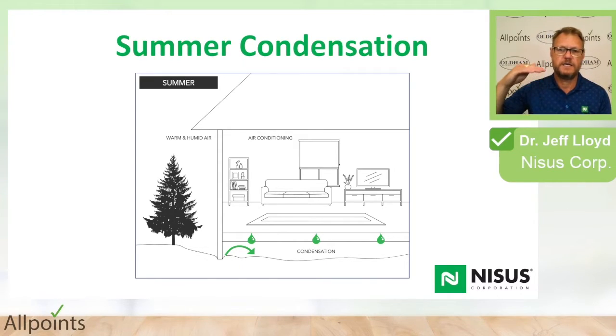And if you think about a thermostat on a wall, that might be set to, let's say, 72 degrees Fahrenheit. Well, the floor temperature is probably only 70 degrees Fahrenheit because warm air rises, cold air sinks. So your floor joists in that subfloor are going to be cold. And if that temperature is below the dew point, you will get condensation in that crawl space, and that will then lead to mold growth and fungal decay.